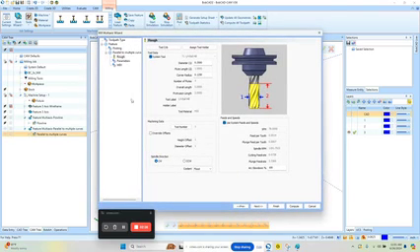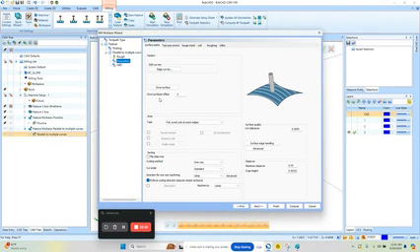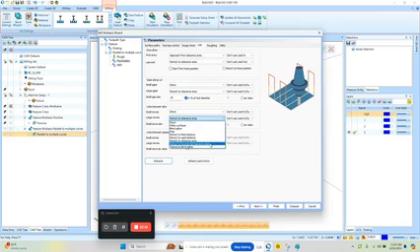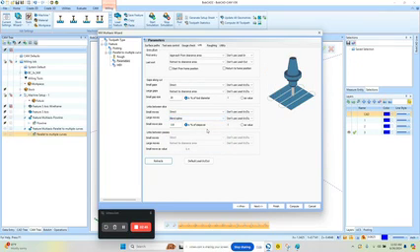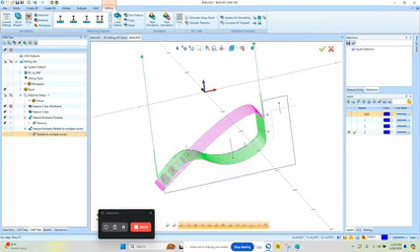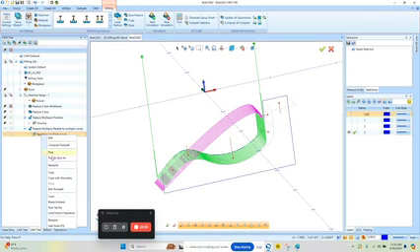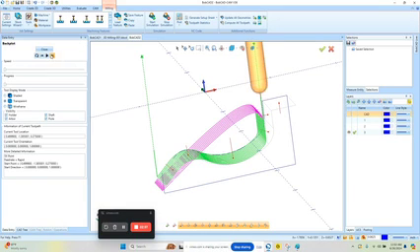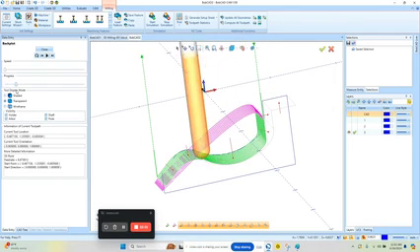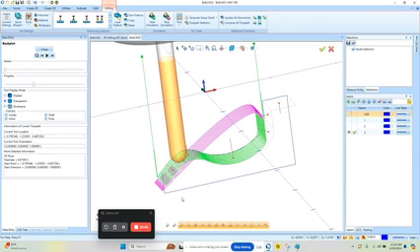So we're going to come into here, go to parameters, links, blended spline, compute. So that gives us this scenario, but if you notice, we're going to end up rapiding through the part, right? So we need to make some additional adjustments in order to fix this problem, essentially adding a lead out so that we can have some clearance on the tool.